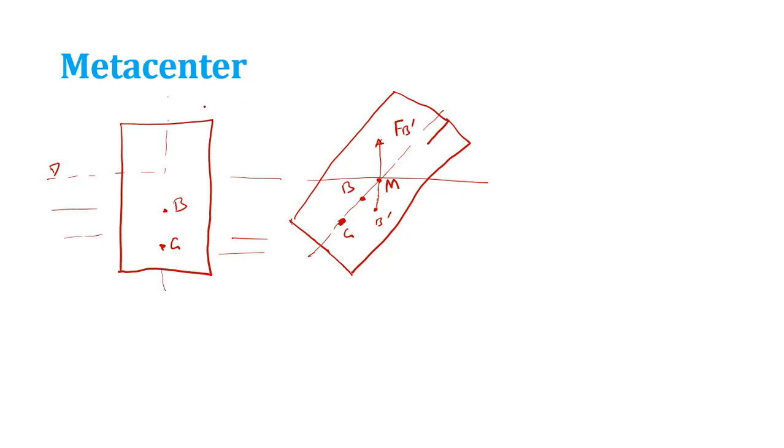So if I have rotated this in this direction, right? Because it is a partially submerged body. What is the difference between fully and partially submerged body? Just now we have studied fully submerged body, and now we are studying partially submerged body. So what is the difference between these two? In this case the center of buoyancy after rotation will change. That is the one big difference between these two cases. And you try to write this concept, it's very important.